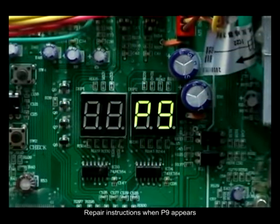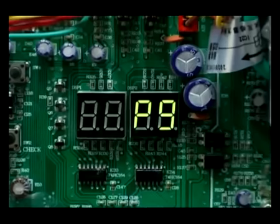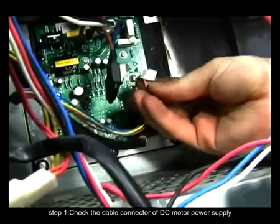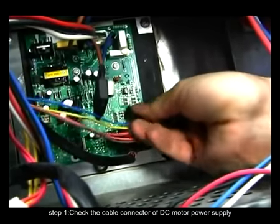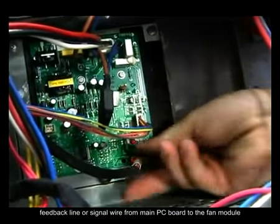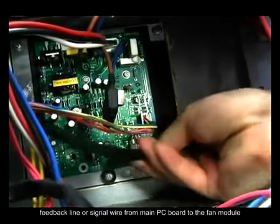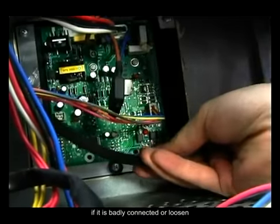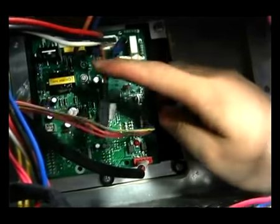Repair instructions when P9 appears. Step 1. Check the cable connector of DC motor power supply, feedback line or signal wire from main PC board to the fan module. If it is badly connected or loosened, fix it. If it is normal, please go to the next step.